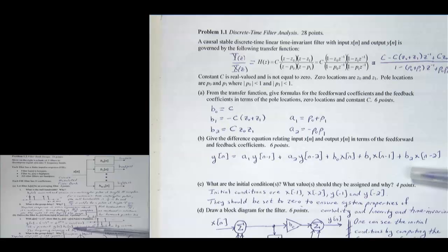So the product in time means that it's a modulation. It's a modulation problem in disguise. It's cosine modulation. I'm just multiplying cosine pi n times h0[n]. And whenever I multiply, and we didn't do this explicitly in the time domain, but from the intuition from the continuous time case back to homework 0, if I multiply by cosine in the time domain, I'm going to shift the Fourier domain by the frequency of the cosine, left and right.